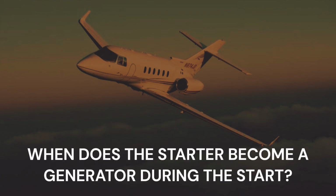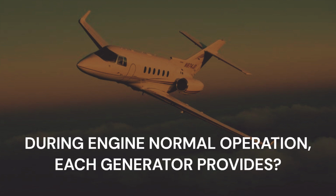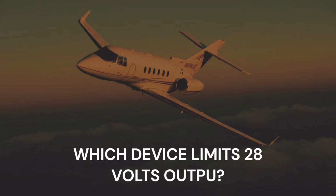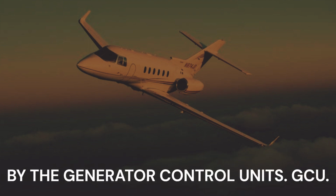When does the starter become a generator during the start? Approximately at 46% N2. During engine normal operation, each generator provides 300 amps and 28 volts. Which device limits the 28 volts output? The generator control units.